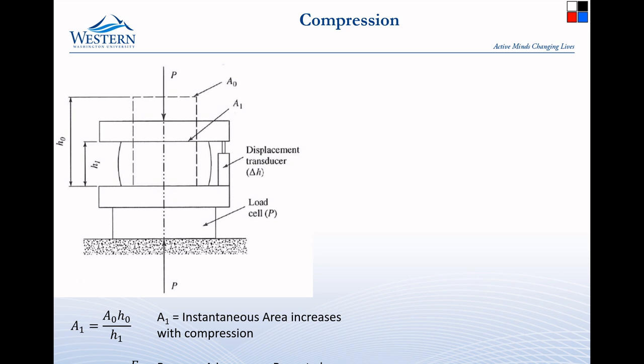And it is just the internal structure of that: when you stress it in one direction, it moves the alternate way in the other direction. And it doesn't violate the constancy of volume because it is not a fully dense material. The structure has space in there. It's also why cork boards work, where you put push pins in them. When you push it in, you're applying the stress, it kind of moves out of the way, and then when you release the stress, it re-expands and it grabs the end of the pin.